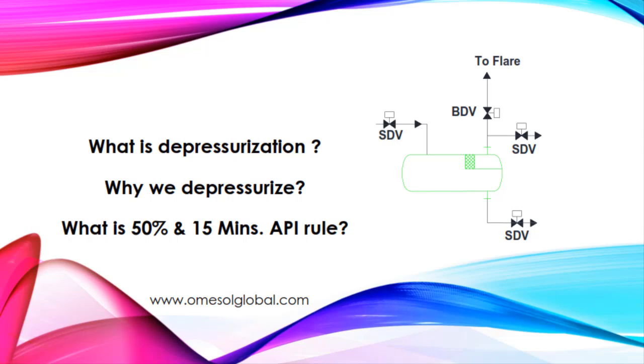Depressurization is a very important topic with respect to the oil and gas industry. So, the question is, what is depressurization? Let's assume there is a two-phase vessel which we want to depressurize. The inlet line to the vessel has a shutdown valve. The vapor outlet and liquid outlet lines also have shutdown valves. If I want to depressurize this system, I have to close all the shutdown valves.